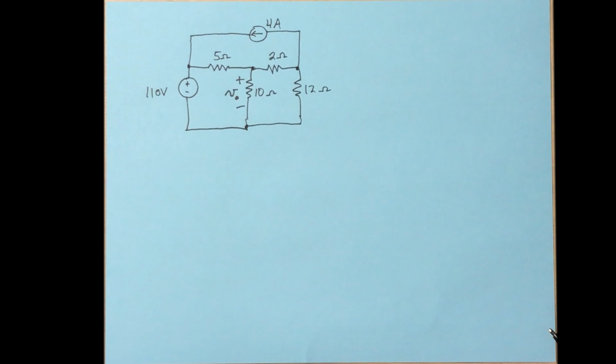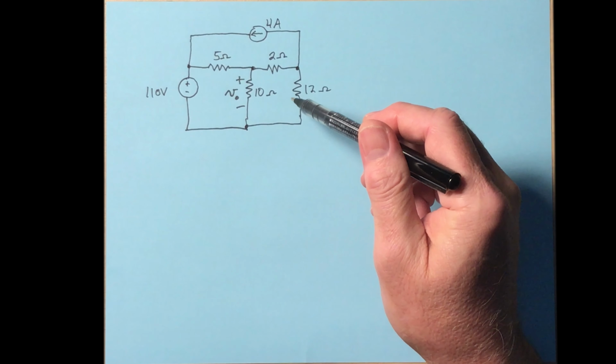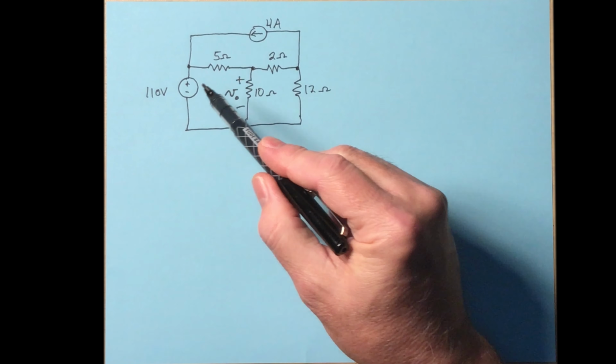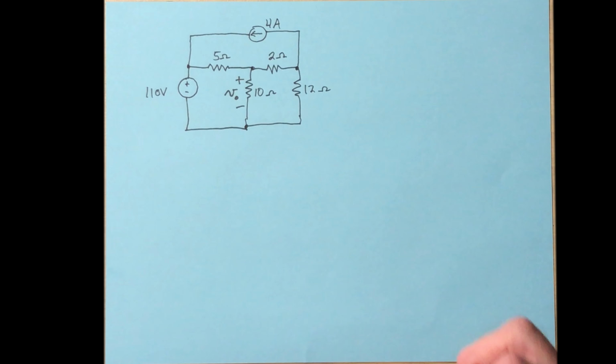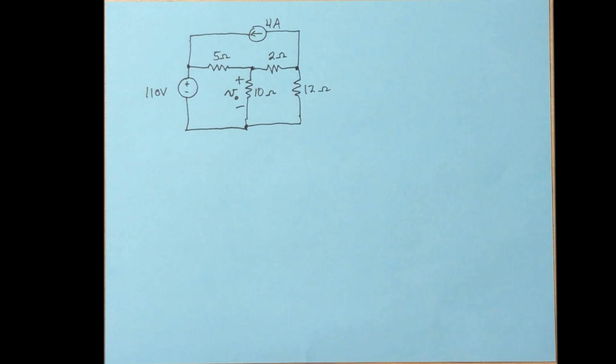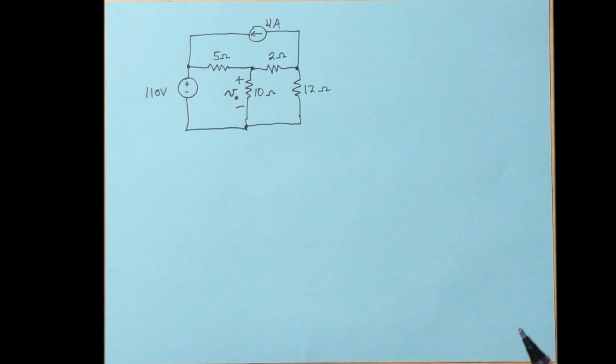Now, that's the principle of superposition. So the voltage across or the current through an element in a linear circuit like this is just the algebraic sum of the voltage across or the current through that element due to each independent source acting alone. If we wanted to solve this circuit using superposition, we would have to solve it twice. That's a major disadvantage of this technique.